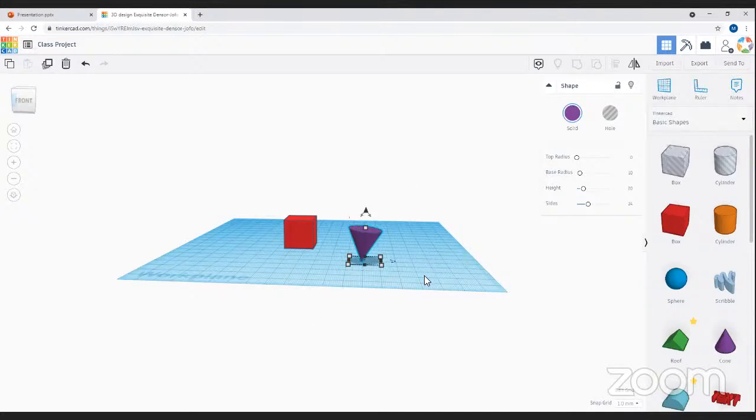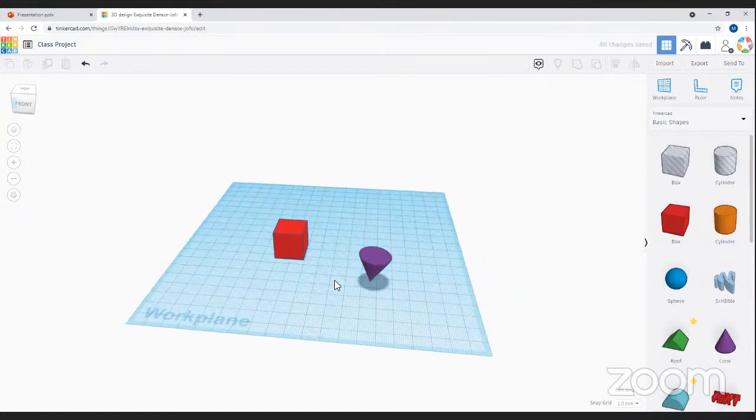So when you're making designs, you want to think about the best way so that when it prints, you don't have to have so many support systems, that it will just print naturally and have as few problems as possible going forward. So instead of printing something like this, that has no wide base and has to have a lot of supports, I usually recommend that you print something closer to this, where there's a lot of flat surface on the bottom for it to work with.